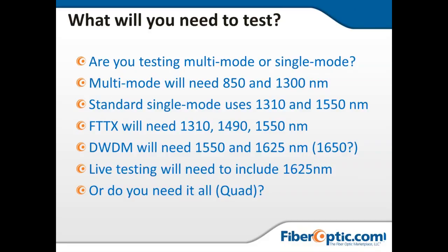Again, we're looking at the two wavelengths here because one of these wavelengths will be the wavelength that we will operate under, right? So if we're operating at 850, we want to know what the fiber looks like, how clean the fiber is at that particular wavelength. So we'll want to make sure we use that as one of the measurements.